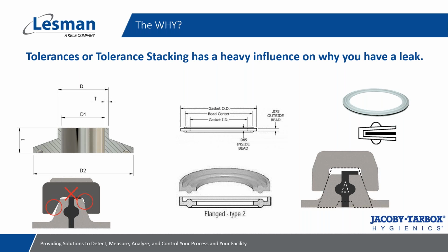And that clamp in its own right has design features and or lack of design features that can accommodate those things. So when we talk about tolerances and tolerance stacking, it's not that any one of the products that you have are necessarily bad or out of tolerance, but the fact that one could be on the smaller side of the tolerance and one could be on the larger side of the tolerance, and now we're trying to mate them together, that starts to contribute to the problem of making things not fit perfectly.